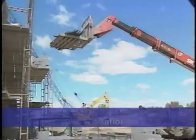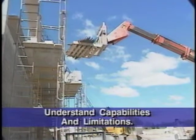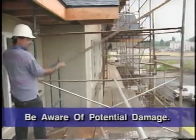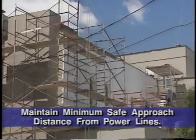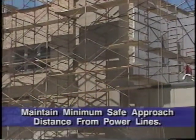Understand the capabilities and limitations for the scaffolds you use, including load capacity. Be aware of any potential damage or defects to the scaffold during use. Always maintain the minimum safe approach distance to power lines. If you must work near power lines, have them de-energized or moved.